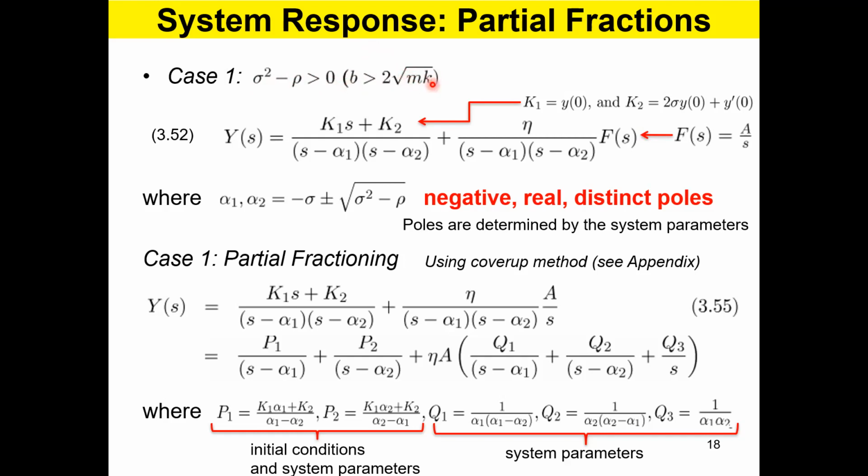And K is the spring, right? Spring is now weak. Spring means oscillation. The moment you think about a spring, what comes to your mind is oscillation. So this is a situation where you don't get oscillations, but the system is very slow because of the high friction. This is like a very high friction damped system. So therefore motions are not easily possible. Okay. So before we even go for mathematical derivations, we can understand what is to be expected. Okay. So that approach is extremely important for a rational person, and particularly for engineers.